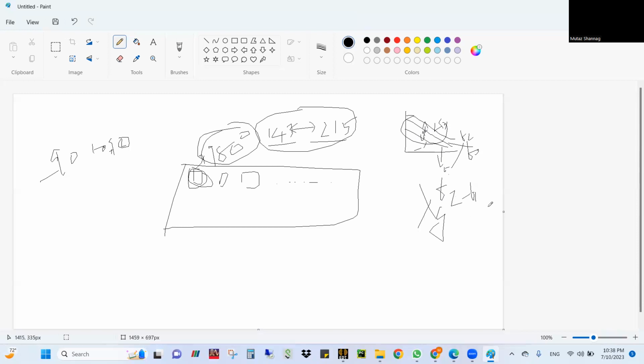So what you can do is plot the phase versus frequency, whatever the unit cell size or frequency may be. You are having a curve like this. You take minus 90 and plus 90, and the corresponding frequency range is your bandwidth. That's it. So why are they considering this minus 90 to plus 90 for bandwidth?